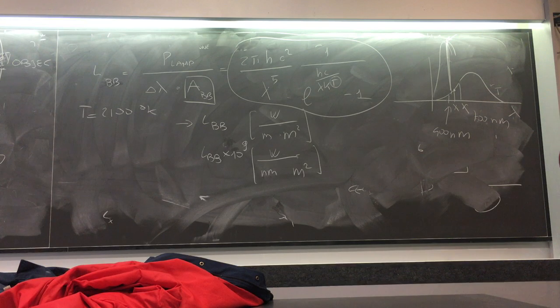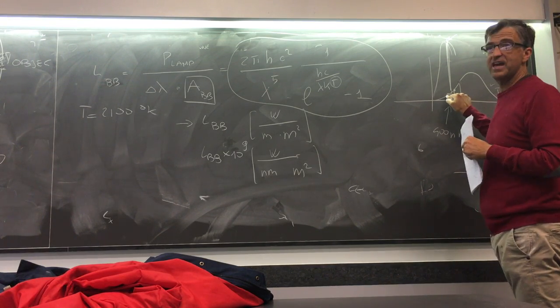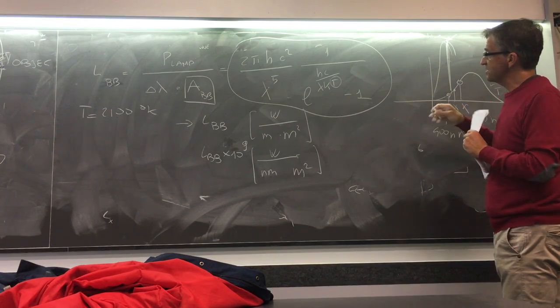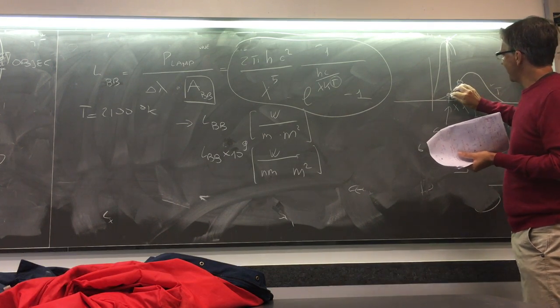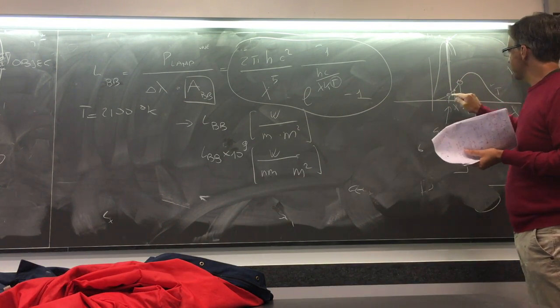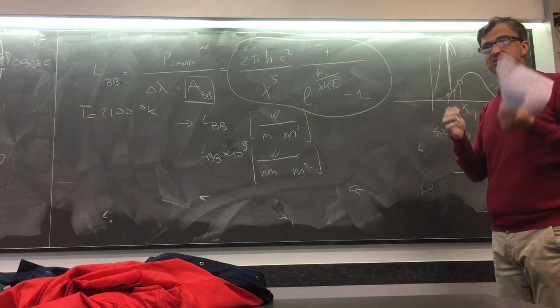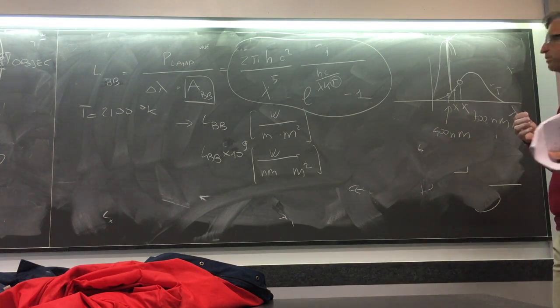And so when you have a photo, usually the camera does a compensation for the light. It's called white balancing. What is white balancing? Since they know that there is much less energy at the blue with respect to the red, they find a white object and try to change the energy, the gain per color, in order for the white part of the image to be white.